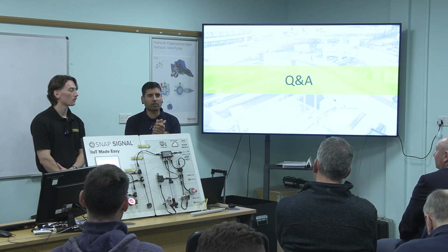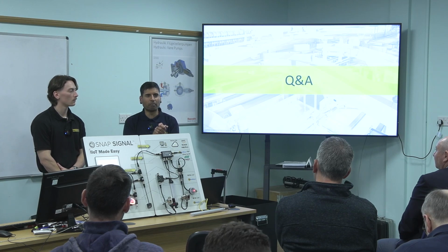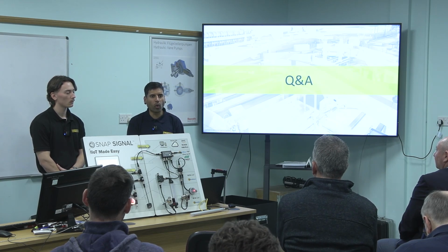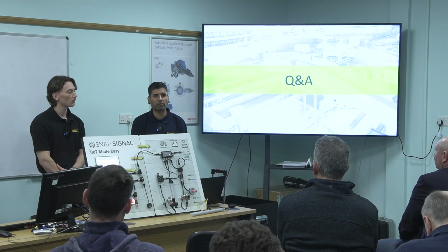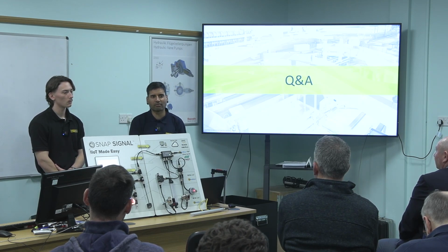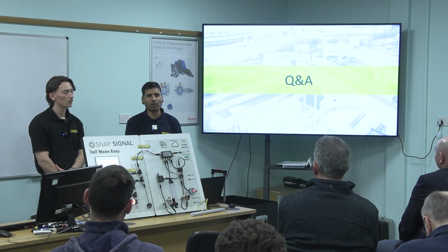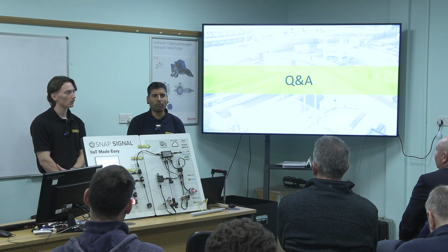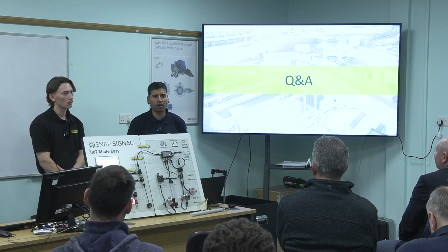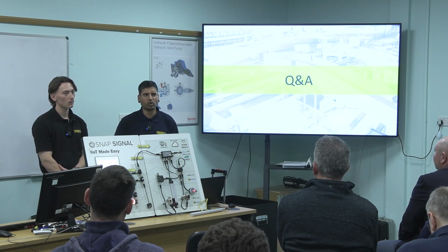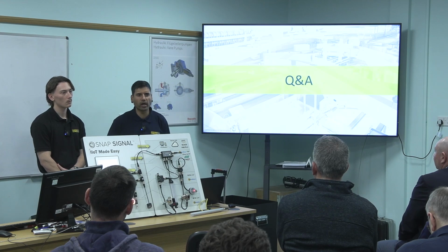If you're connecting it to a PLC, you could send any of that data back to the PLC. But really, what we find is this is for predictive maintenance, and it's not really a PLC. It's just a way of capturing the data. We don't expect you to use this instead of a PLC because it's not got that sort of memory as a PLC or a computer. We just use it to capture signals from your machines, your critical signals like vibration and temperature. Your PLC will do more of the process work and the hard work.